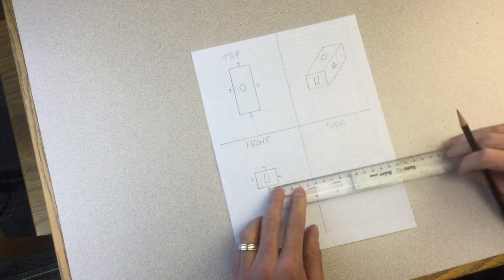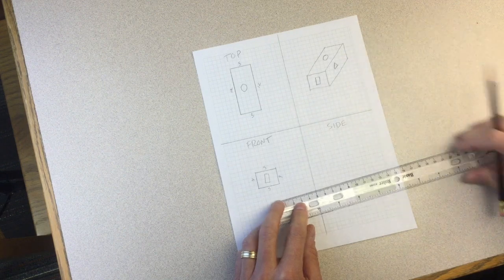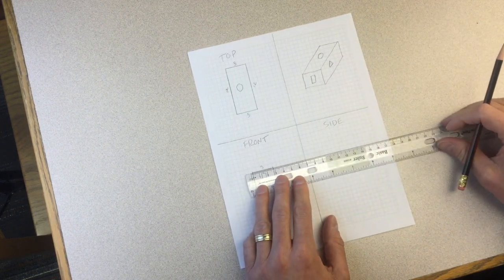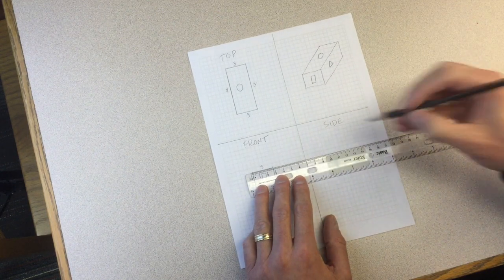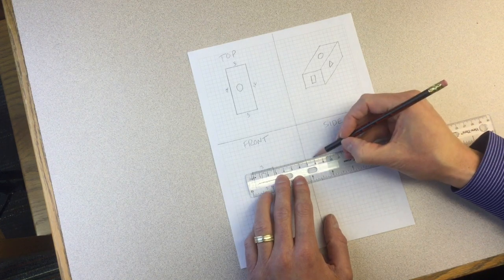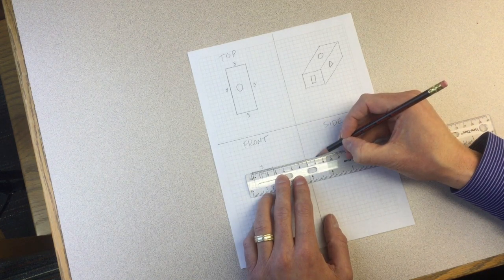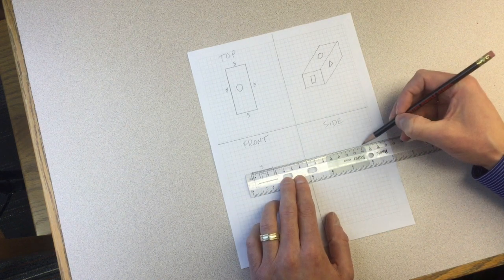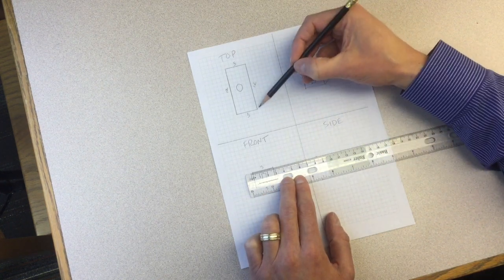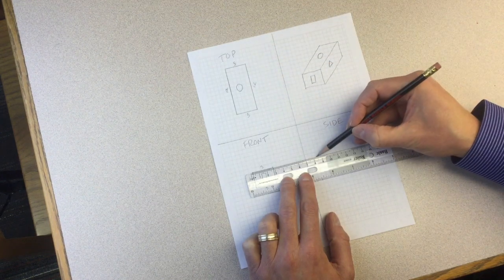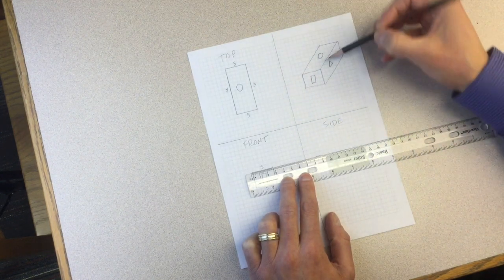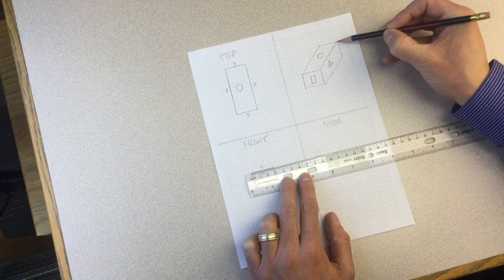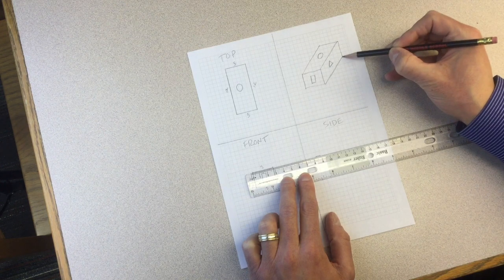Okay, so then the side view is this view right here, the one with the triangle on it, and I know that has to line up with this. So that will start, let's say, right here. Okay, and how do I know how long that's going to be? Well, I've already made that side up here. It's 12 squares long. Good, because it's going to be the same length here. This edge is going to be the same length as this edge.